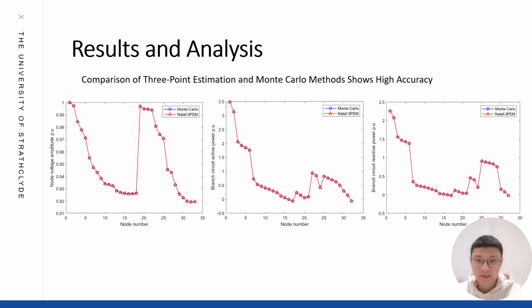After integration of distributed generation, the voltage magnitude at node 18 and node 33 shows a significant increase. As for branch 17 and branch 33, the expected values of both active and reactive power are negative due to low load at the end, and the integration of wind and photovoltaic power results in the reverse flow of the active and reactive power back into the system.